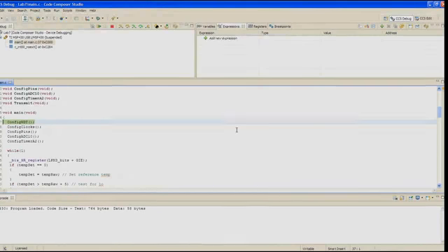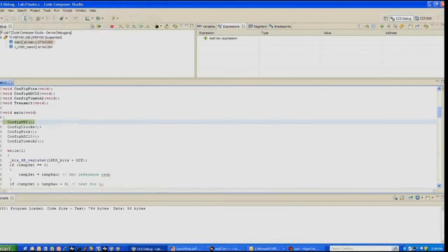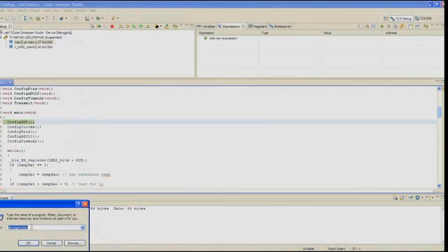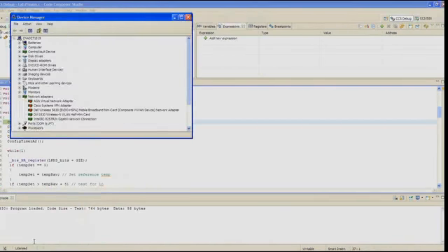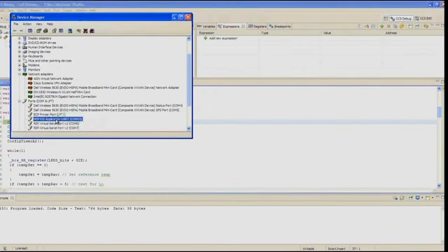In step 21, next we need to find out what COM port your LaunchPad is connected to. This should be the same as earlier. In Windows, click Start, Run, and enter devmgmt.msc in the dialog box, and then click OK. If you're running Windows 7, you can type Device Manager into the search window at the bottom. Click the symbol next to ports and find the port named MSP430 Application UART. Go ahead and write the COM port number down in the workbook here. We got 22. Go ahead and close the Device Manager.